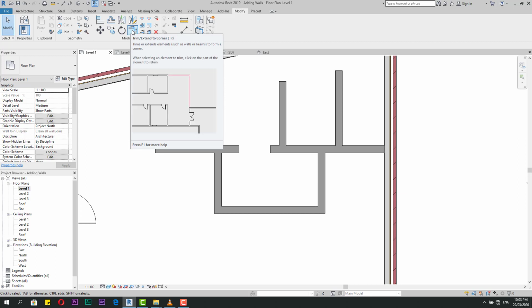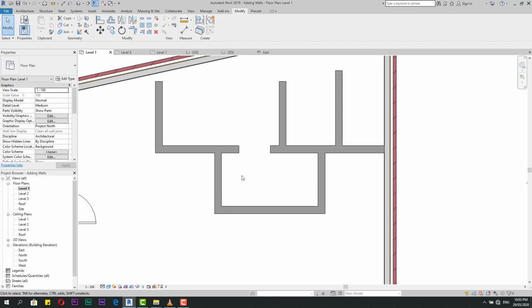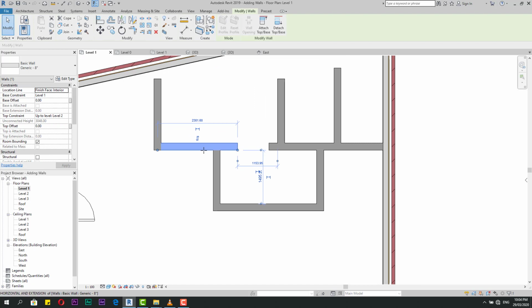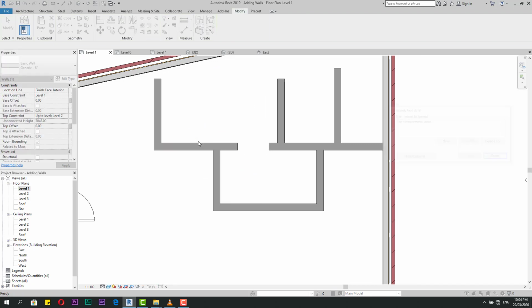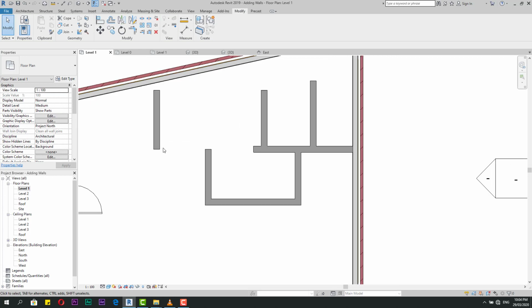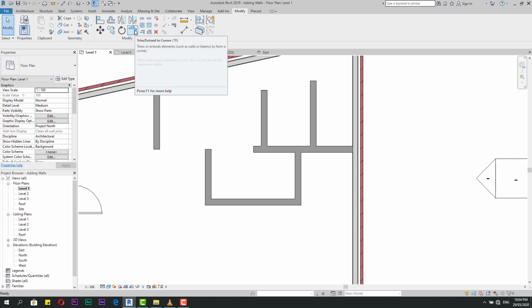Okay, what's the meaning of trim or extend? This is used to make a clean, highlighted corner. Okay, as an example, if I have this, I will delete this. If I need to close this with this, I can draw directly, or to save time I can use fillet.